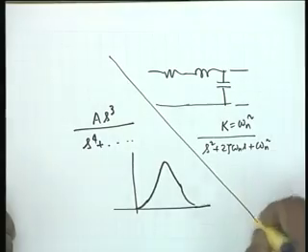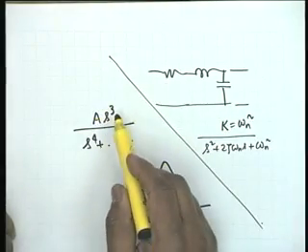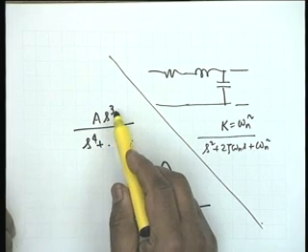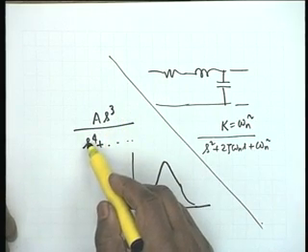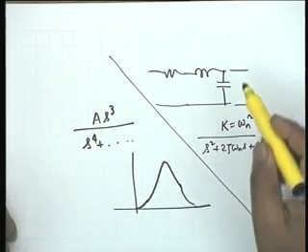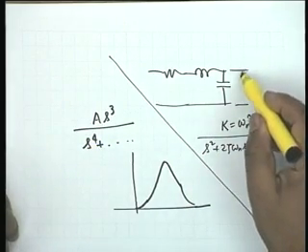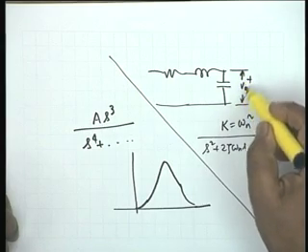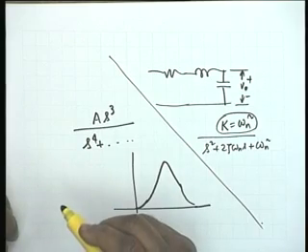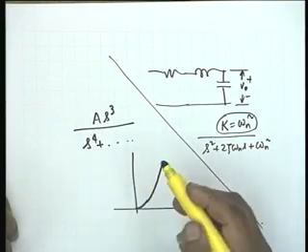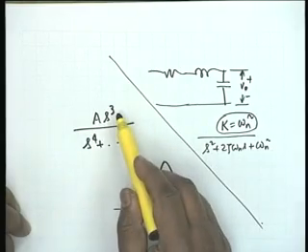The difference between single tuned circuit and the double tuned circuit is that the transfer function in the double tuned circuit has an s cubed in the numerator, and in the denominator has an s to the fourth. Whereas in the single tuned circuit, the case that we considered, we took the voltage across the capacitor, V0 was here, and the transfer function had a constant in the numerator. So, the DC response, that is, put s equal to 0, this value is 0.